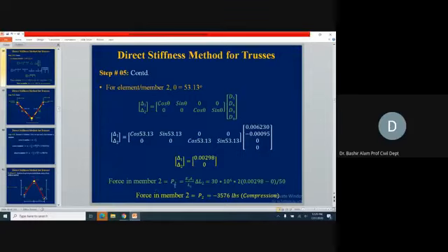So this is coming 0. Axial force in member 2, which will be P2, will be equal to E2 A2 divided by L2 times delta L2. So this is E2. A was 2 inches square. Delta 2 now, this should be equal to delta 2 actually. This should be equal to 0 minus, this is now a mistake here.